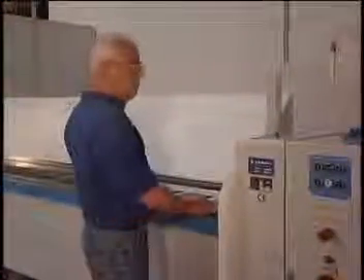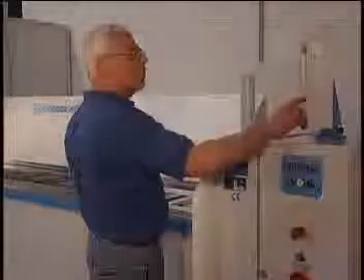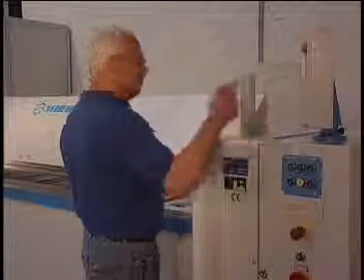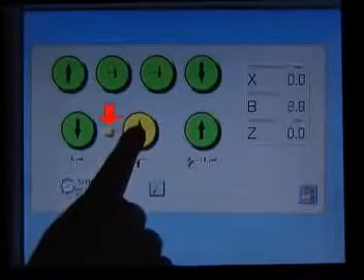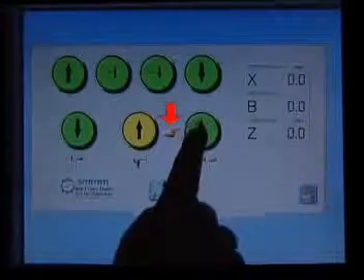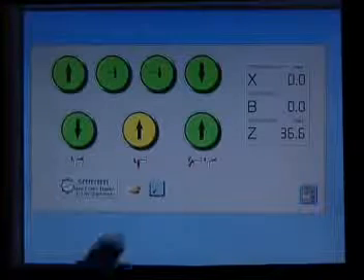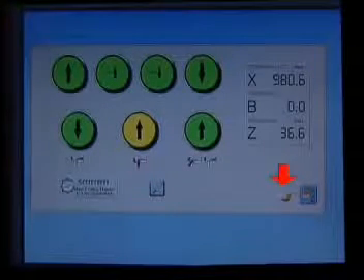After turning on the machine, the startup screen appears. The control has to be calibrated after each startup. Follow the cursor finger and push the upper beam down button, then the bending beam button, and again two times upper beam up. Finally, push the back gauge button. Start the actual bending program.